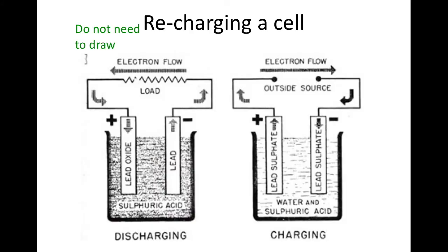This is a lead-acid cell, also known as a lead-acid accumulator. Accumulators are most familiar to us as large, powerful car batteries. A lead-acid accumulator contains 3 or 6 separate cells inside a tough plastic casing. Each cell contains lead electrodes that are plates. The first plate is of metallic lead, and the other is a plate of lead oxide. Both plates are placed in sulfuric acid, which is the electrolyte. During operation, the sulfuric acid is gradually turned into water, and the lead electrodes react with the acid to form the product lead sulfate and 2 free electrons.